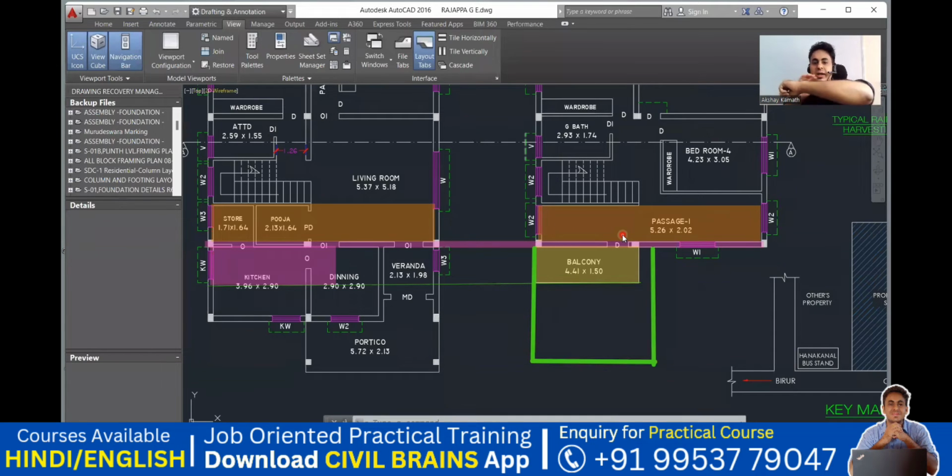This particular area is this one, and here I cannot take a cantilever of this length. What will happen if you put it? It is going to fall, because there is no back anchorage to that. So cantilever, max to max, you can go with 1.5 meter or 3 feet. That is why it is only 1.5 meter. So that is the reason you can see it is only up to here, because this is only this much cantilever I can take. I cannot take a cantilever like this. If you take a cantilever like this, then the thickness of your slab will be huge. So in order to reduce that thickness, we can only give this much cantilever, which is 1.50 meter, roughly around 3.5 feet, and that's a good cantilever length. You can keep it.